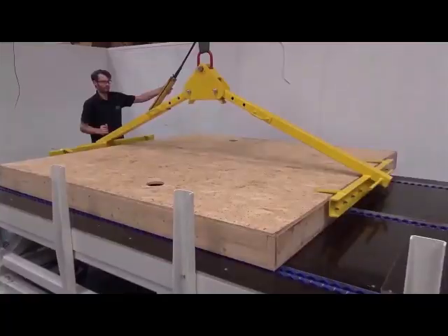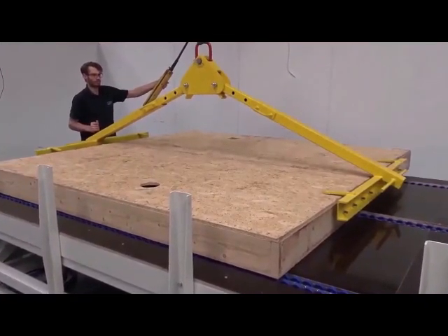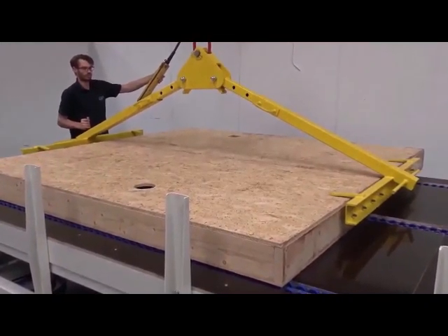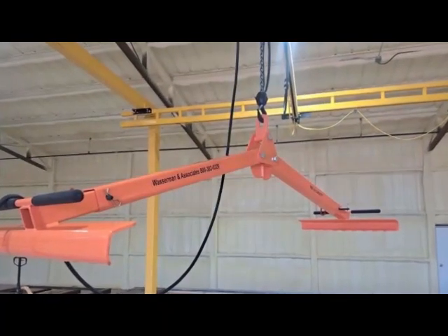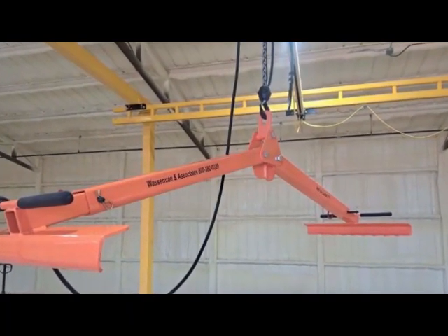So some of the things we must have in mind while handling our panels is that we must move our panels with a lifter. We must place our panels on a flat surface, and we must ensure not to drag our panels on the floor. For some panels that have a protective nylon film on them, we should always ensure we complete our installation before removing these films.